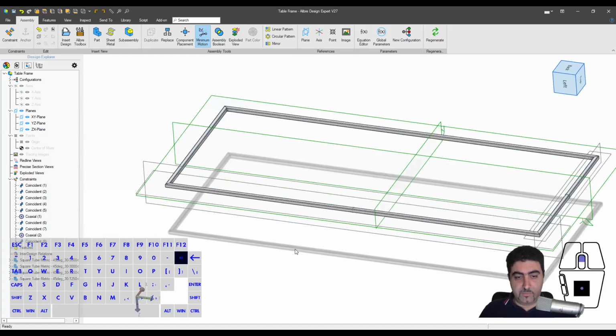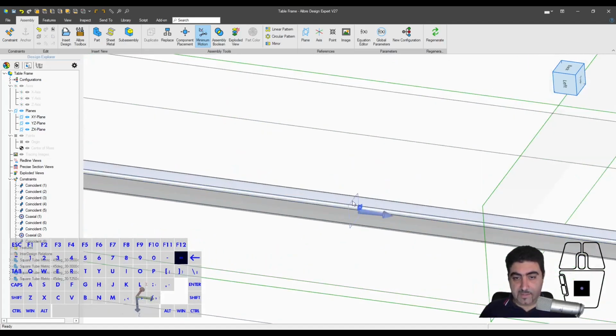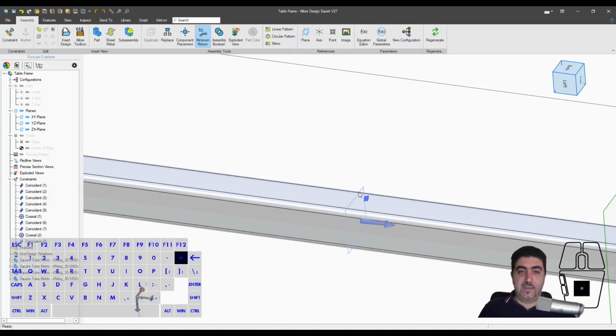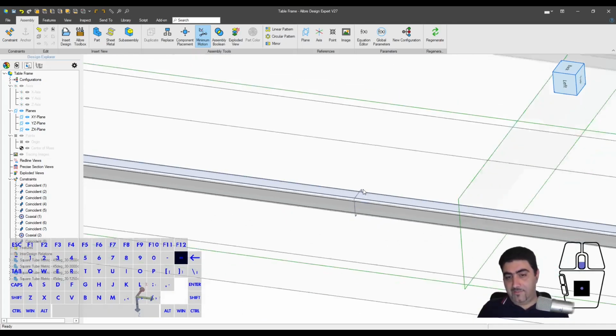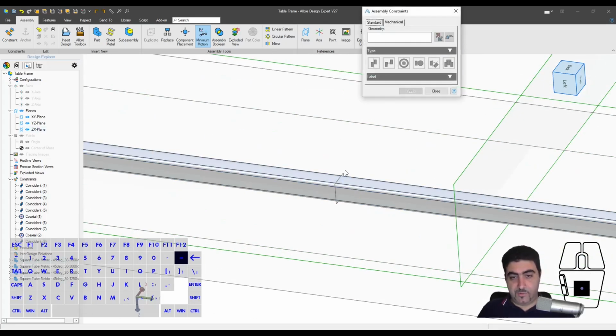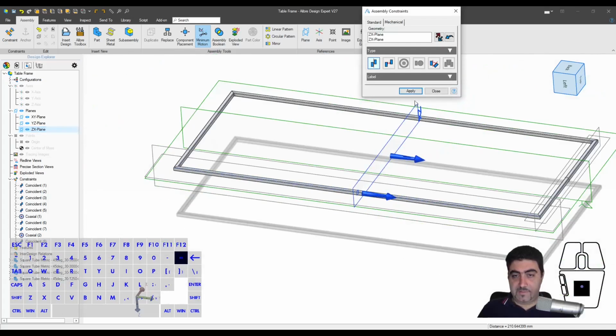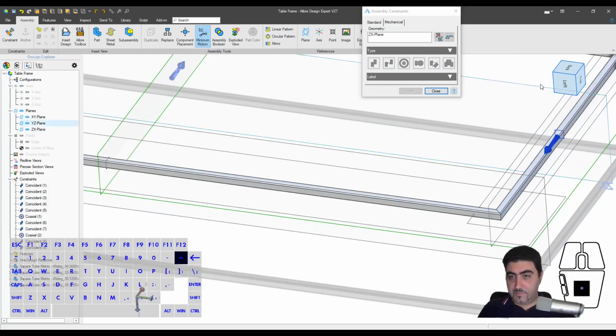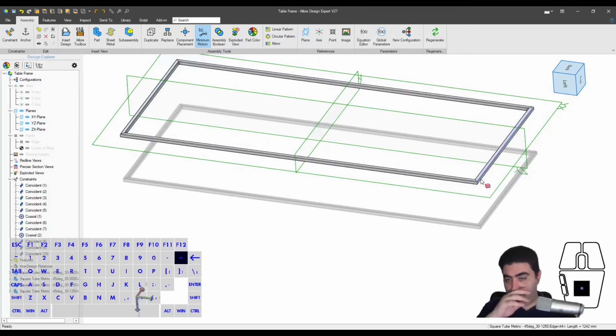And the way this is going to work, right? You see this little plane, because I made them as a mid plane, the extrusion when I was designing it, I have a mid plane now, right? And this is a win, because if I didn't do that, I would still have a reference here and a reference there, but I wouldn't have the middle reference, which now I do. So let's assemble this to this, assemble this to this, turn off the referenced files, and look what I have.